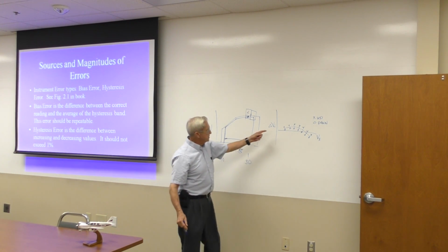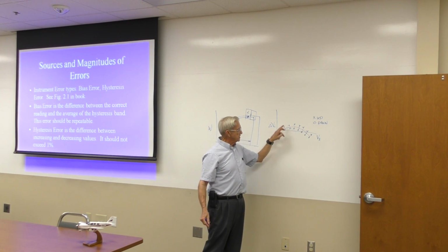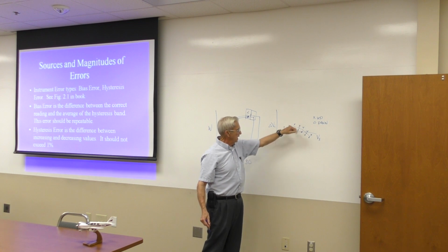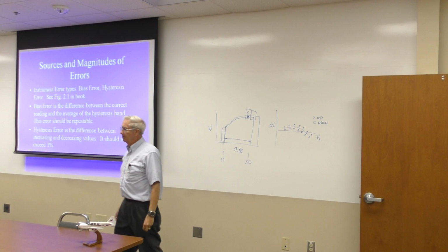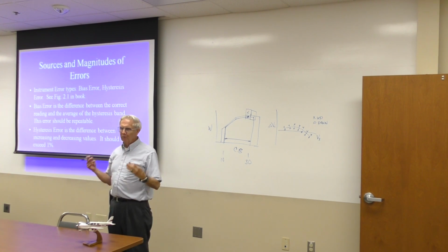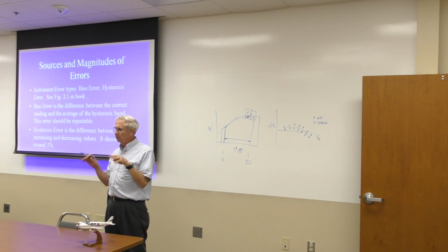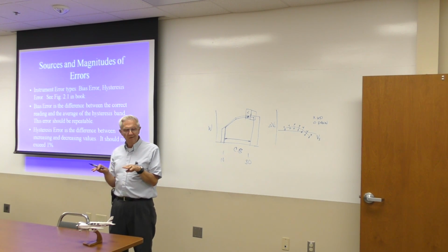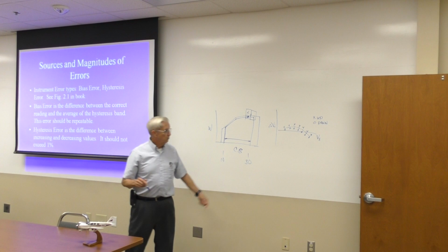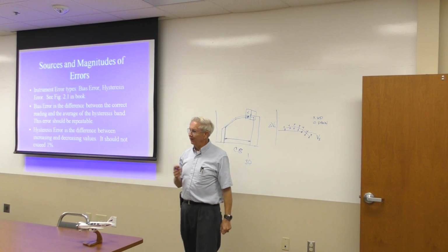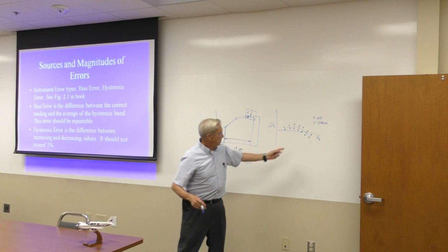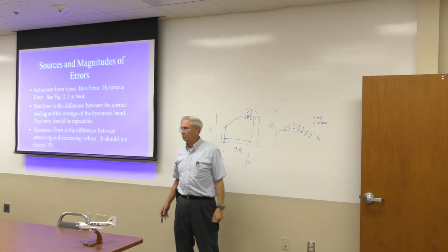Okay, if we're increasing airspeed, and these were increasing airspeed points up here on the X's, then we'd use that value. If we were in a stabilized situation where we'd been sitting there for a while, then we'd use the middle. If we were decelerating or decreasing, we'd use the bottom.